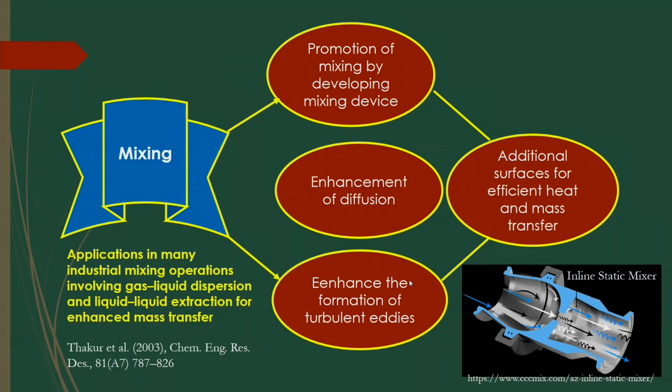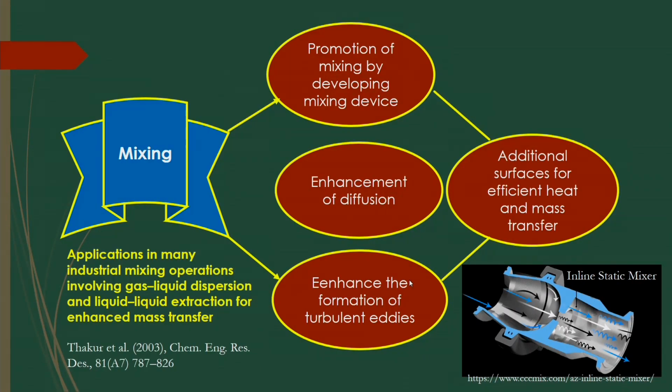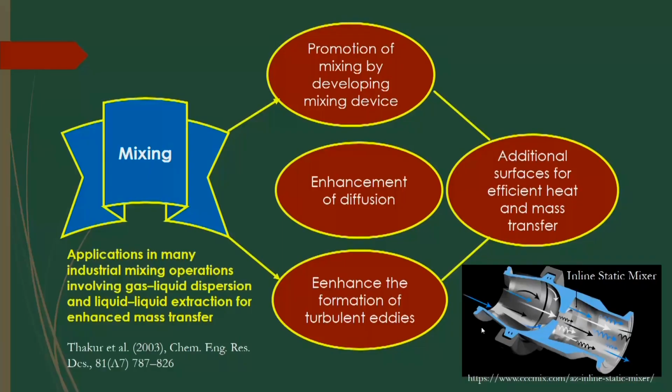Also another phenomenon is mixing, promotion of mixing by developing mixing devices. You have to improve the device to intensify the mixing of the fluid. In that case you can get enhancement of diffusion, you can get more turbulent eddies whenever turbulence in the fluid mixing is generated by that particular design of the devices. Even additional surface area you can get based on that fluid mixing, which will give you efficient heat and mass transfer for that particular operation.